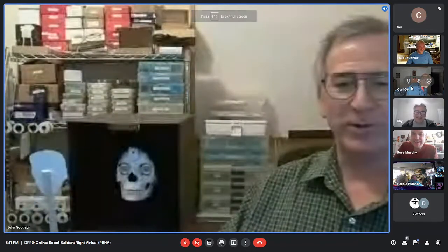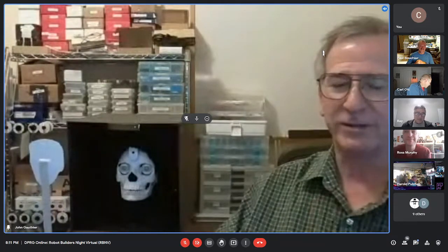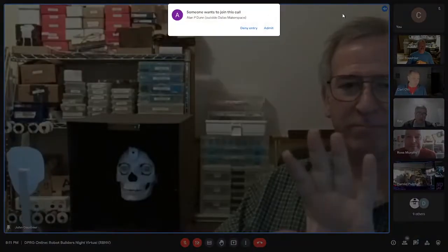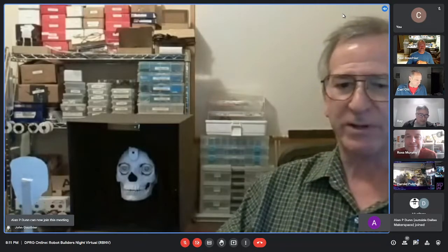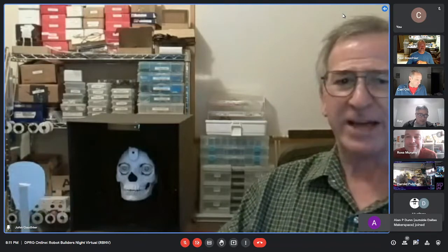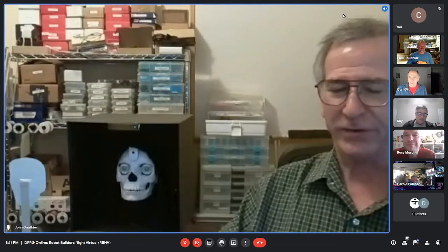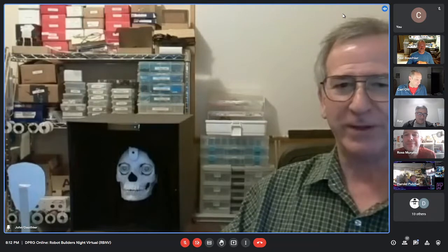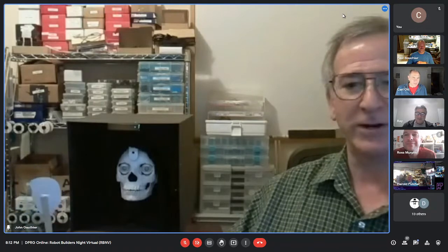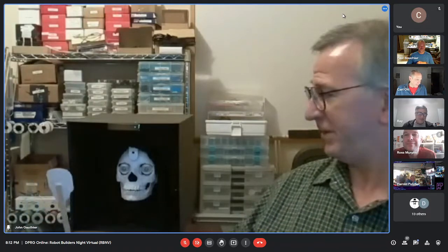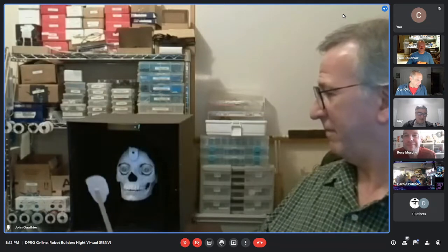So I've got three modes. When the face is far out, I use the size of the box that it detects around the face to determine the mode. If it's at a certain distance out, it's just kind of what I call relaxed, tracking with the eyes. When you start to get closer, the eyes start to narrow. I'll call that suspicious mode, as the eyelids narrow. And then when you get close enough, I've got a startled mode. As I move the face closer here, you might be able to see the eyes start to narrow.